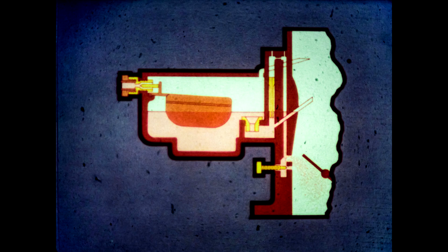When the throttle opens more, fuel flow increases until the main metering circuit delivers the fuel, usually between 30 and 45 miles per hour. This transfer should occur smoothly without fuel flow interruption. However, the float setting does affect the transfer point. If the float is too low, as shown here, fuel delivery through the main circuit will be too late and the engine could hesitate. If the float is too high, flooding can occur.